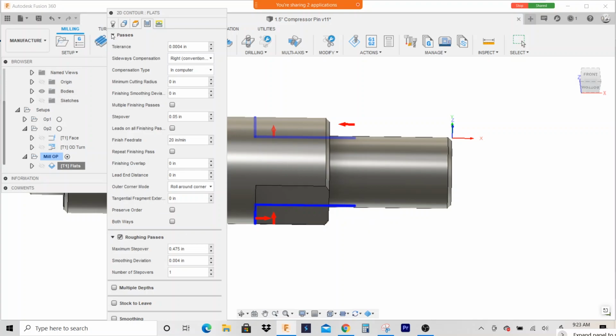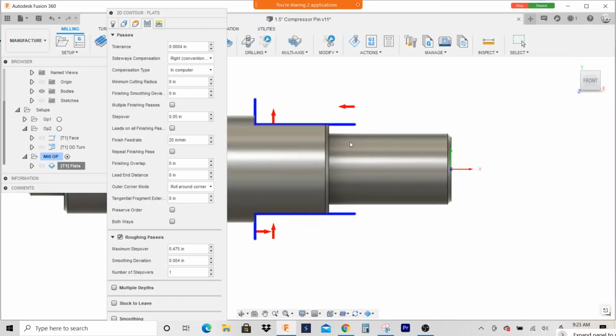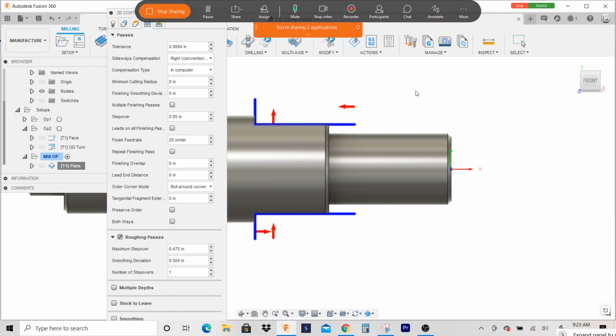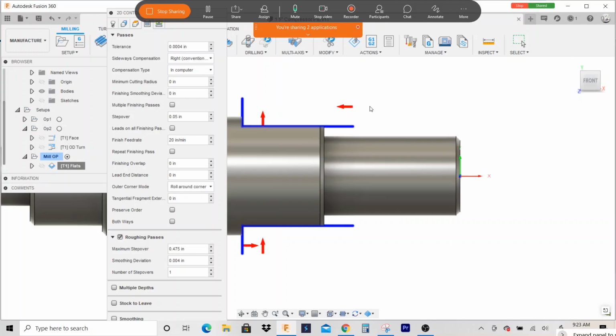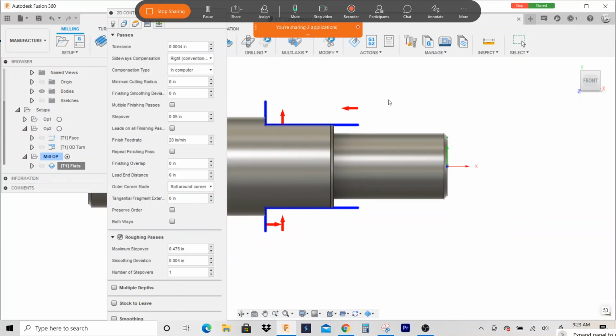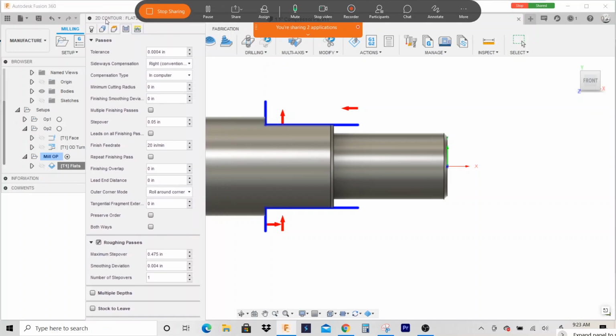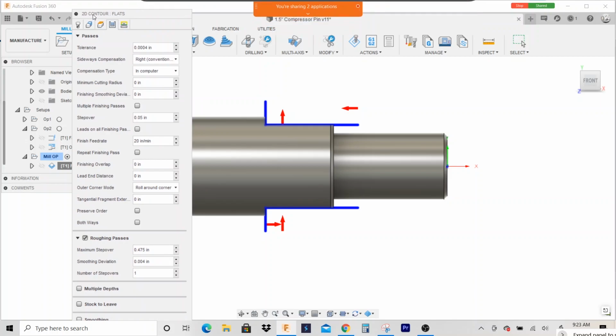Okay, and shop supervisors and production managers can't stand cutting air. So if you're getting a job running a program or as a machinist, you always want to decrease it. You don't want to be cutting air, okay? Unless you're doing the initial setup, the first piece, and you're testing it out, trying to prevent any crashes. Cutting air is no problem in that scenario. But having every part where the tool's coming in and it's cutting air, it's going to increase your cycle time.